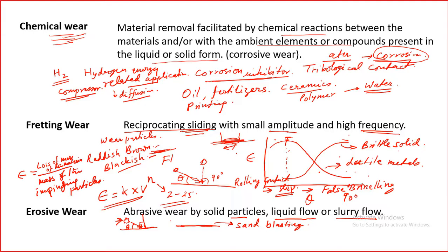So abrasive wear takes place in the case of, for example, dust particles hitting blades of turbo machinery, or in fluid bed combustors where we use particles as a combustion material, and particles in general in steam, wet steam can also act as abrasive particles. So these are the examples where abrasive wear, erosive wear takes place, and we need to design so that we can avoid erosive wear,